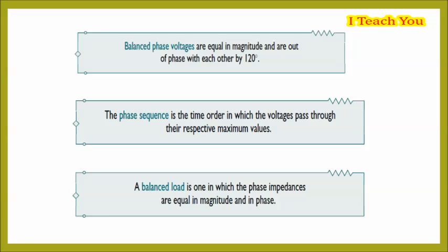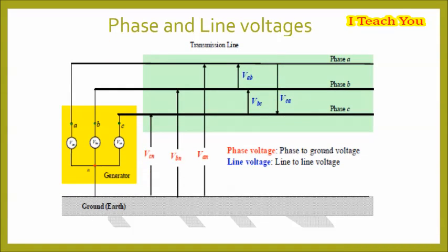The system which has three phases, for example, the current will pass through the three wires, and there will be one neutral wire for passing the fault current to the earth, is known as the three-phase system. In other words, the system which uses three wires for generation, transmission and distribution is known as the three-phase system. The three-phase system is also used as a single-phase system if one of the phases and the neutral wire is taken out from it. The sum of the line currents in the three-phase system is equal to 0, and their phases are differentiated at an angle of 120 degrees.